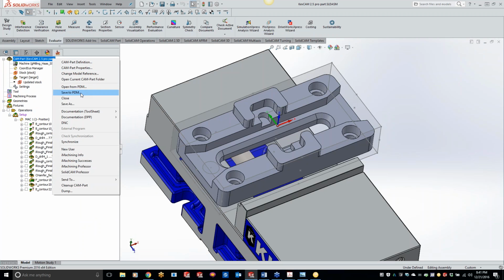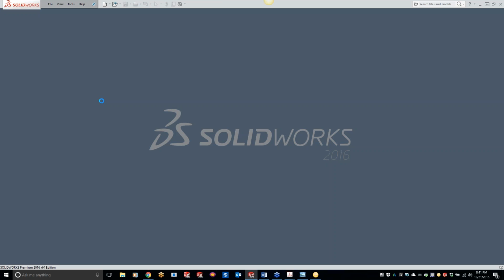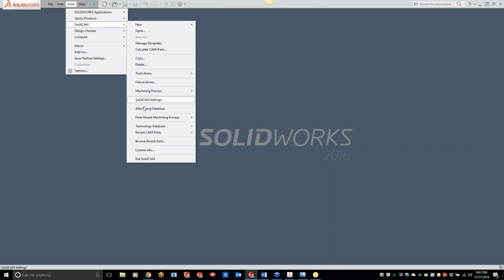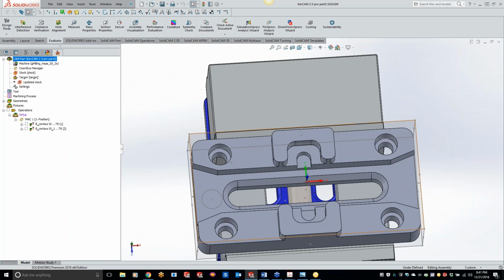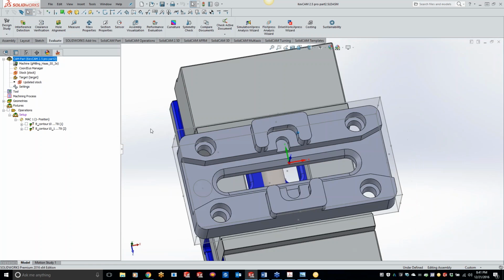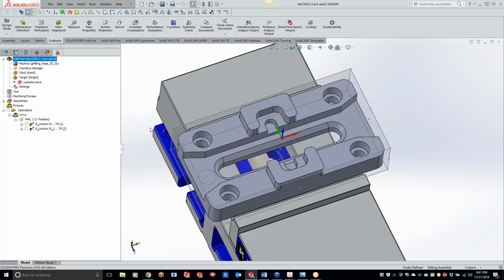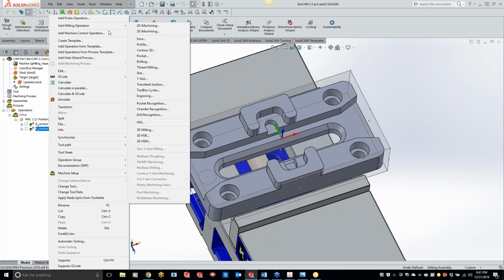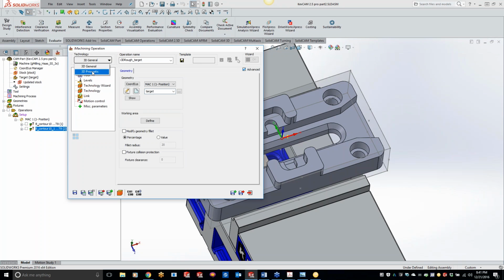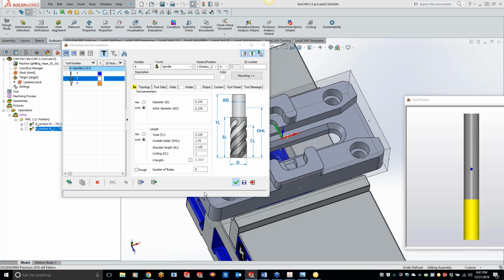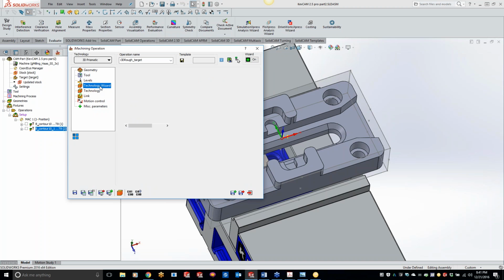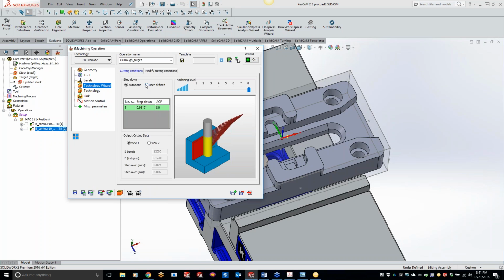Let's get into the best way to do it in 3D. Okay, SolidCAM, recent parts, and we're on part 2. We have our part already probed up, and all I did was make a copy of what's going on here. Go ahead and do our 3D iMachining, grab our tool, hit the green check box. We can do it all in 3 cuts, or I can do different cuts, but I'm just going to leave it on automatic here. Save and calculate.